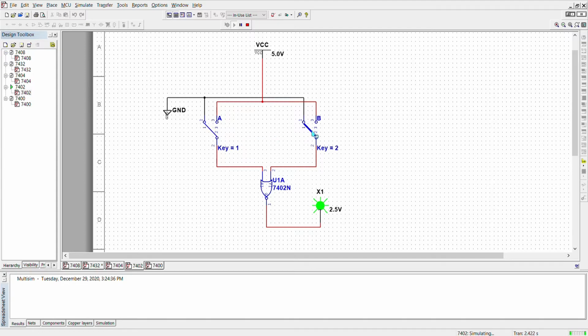As in the lab sheet, firstly, they need the input of A to be 0 and B also to be 0, so the output we will get is 1. Next, we set the input of B to be 1, the A 0, and we will get the output 0. Then we set the input of A to be 1, the B to be 0, and we will get the output 0. And lastly, we set both inputs A and B to 1, and we will get the output 0.